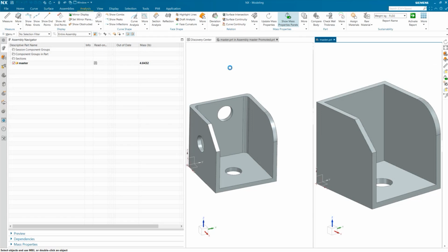So when you're promoting a body, this is where I used it a lot for weldment, because I would come in there, I'd have my master, all these in here, wouldn't have the holes in it yet. And then I'd bring it over to here in a promoted body, and inside that promoted body, I would have my weldment as one piece, and then I'd put the blends or any other cutouts or anything I want to do at assembly level. Now, what you may want to do within the master file here is have some type of note to let yourself know, hey, this is also used in a promotion above.